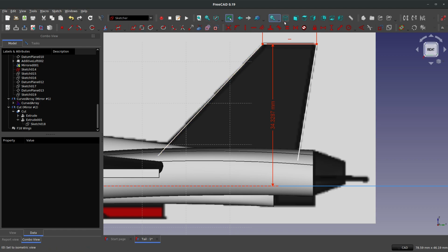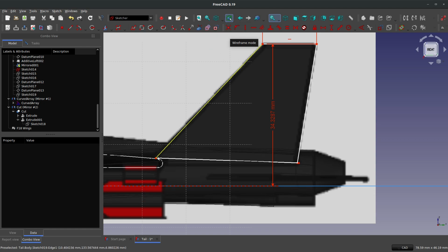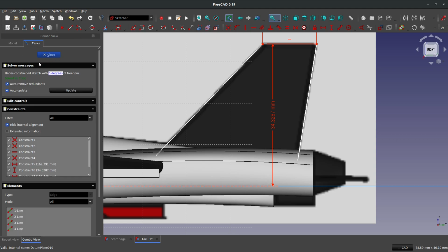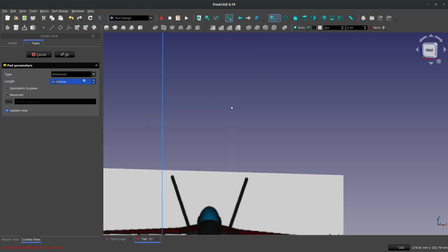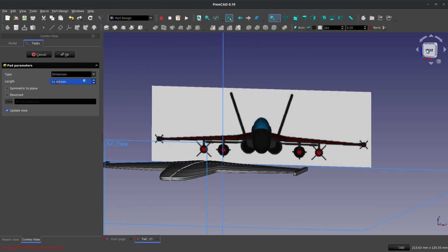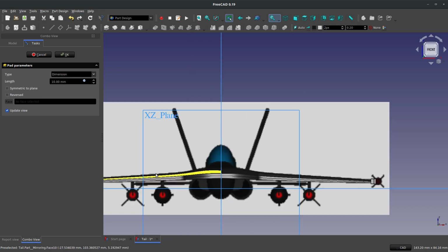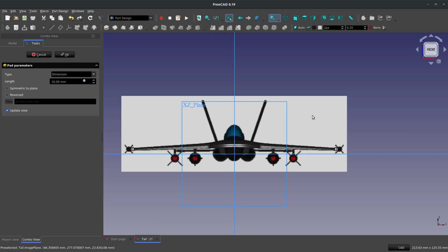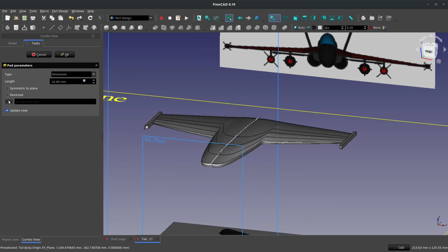I think I'll wireframe this and try to get that perfect. I'll leave these two unlocked so I can adjust easily if necessary. Personal preference. We'll come back to as is, and let's exit our sketch. We'll close. We'll do an extrude. And let me look from the front here. Looks like I've got some hidden bodies. Looks like I have a few hidden things here.